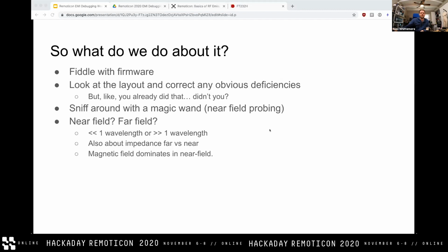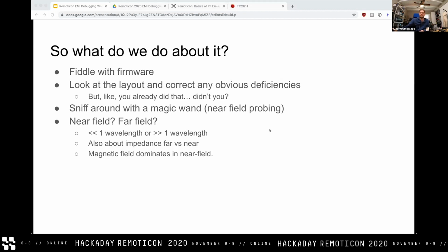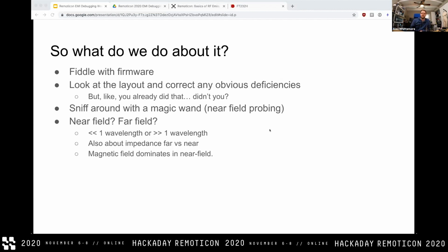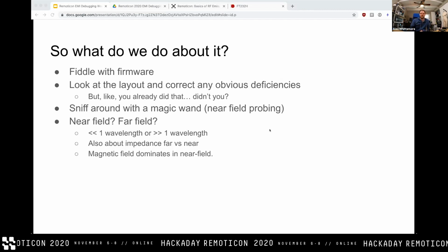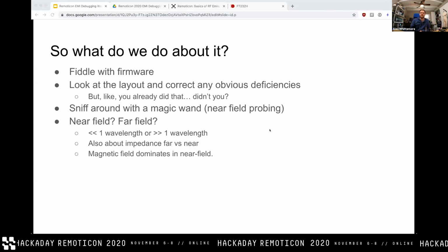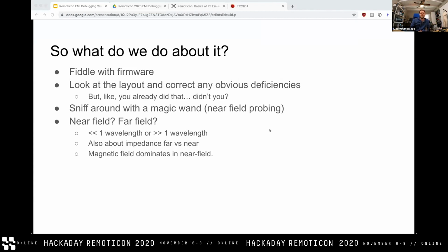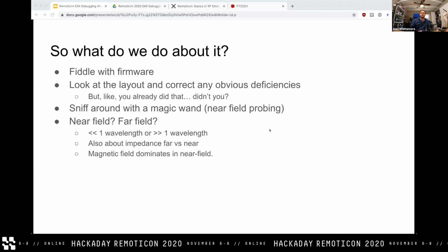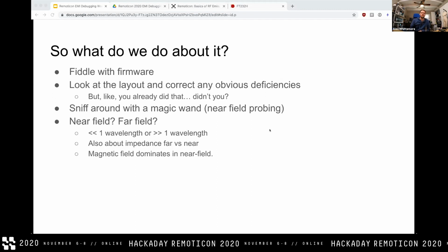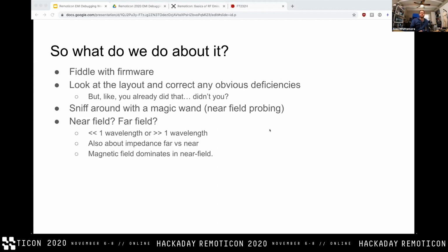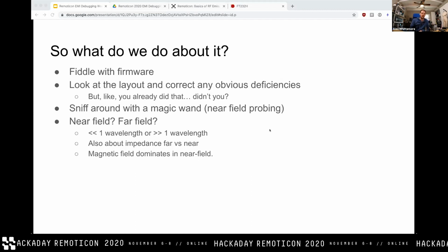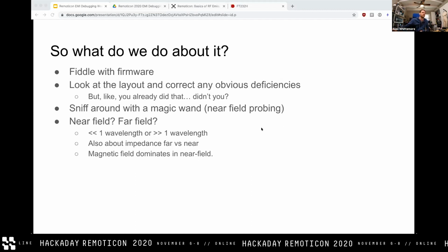And more to the point, you still have to have a point of A/B comparison. Test cells, plenty of testing houses will let you come in and do live debugging and measure your product while you're making physical changes and firmware changes and all the rest of it. But it's super expensive. Time in a test cell is not cheap. Metal walls cost money. So it's best to figure out what you can figure out about how your device works and what might be causing the problem on a bench, before you get to that point.